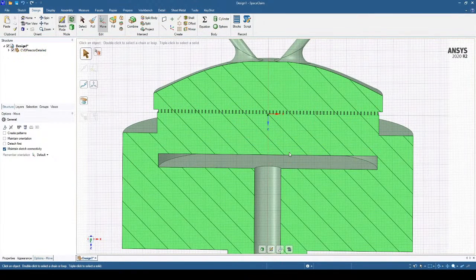The surface is spinning, which is a way to try to have a more uniform deposition, but also changes the flow patterns. You may adjust the temperature on this because the chemical reactions that we look at are highly sensitive to the temperature. And you may want to have a transient pulsing scheme where different chemicals and different reactions will occur to deposit different layers of chemicals and maybe cleanse some of the materials from the system as well.